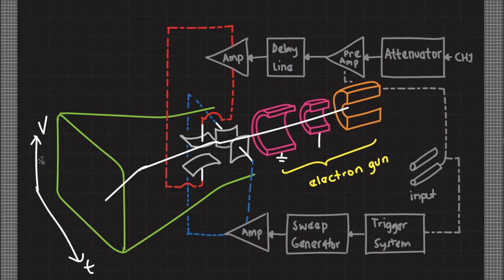And the z-axis, which is not apparent here, actually refers to the intensity. So if you are operating an actual oscilloscope, you can adjust the intensity of the electron beam in such a way that you can view a very thick line representing the voltage signal, or you can adjust it to make the plot or graph sharper.